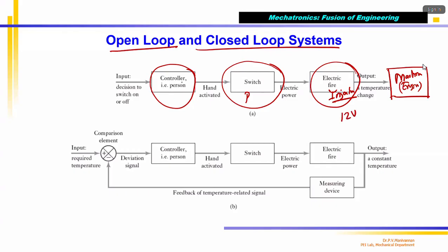The controller, for example an open ECU, is the electronic circuit which generates the pulse width modulation. We call these fuel pulses. The fuel pulses are generated by the controller, which in turn is controlled by the driver input, a mechanical input.